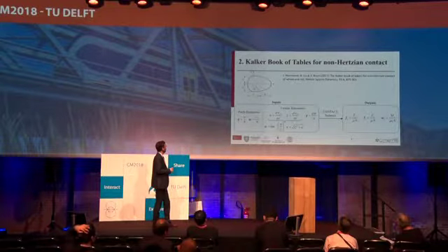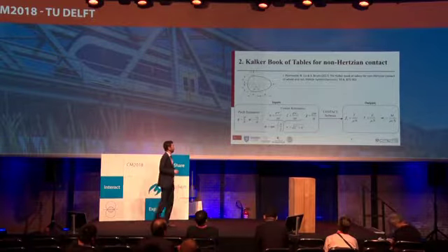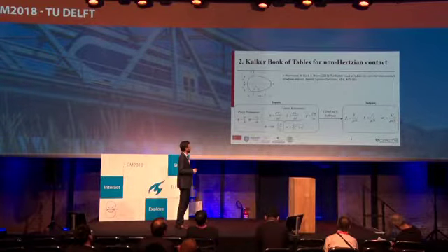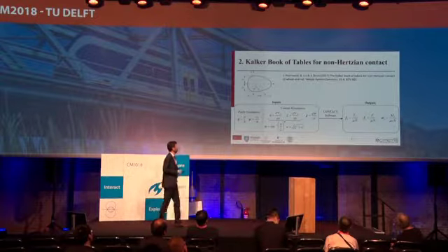So we have overall 5 parameters in our table, 2 for the shape, G and psi, 3 for the creepages, C for the spin, alpha and nu for the linear creepages. And the outputs for this are the non-dimensional longitudinal and lateral forces and the non-dimensional spin moment.